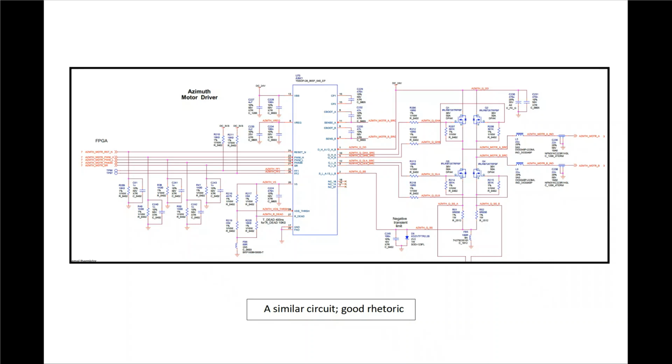Symmetry in the signal path is applied where appropriate, in keeping with the human mind's ability for pattern recognition. The relevant component parameters are all visible. Net names are liberally applied, primarily to make the layout process that much easier and more efficient, but it also serves to make the schematic that much more informative. And notes have been added here and there to bring forth further insight.